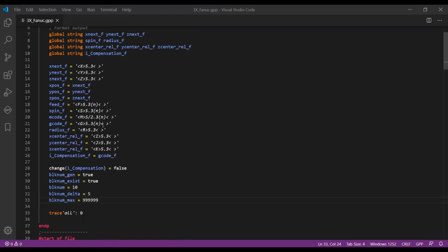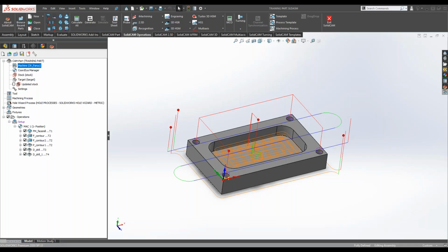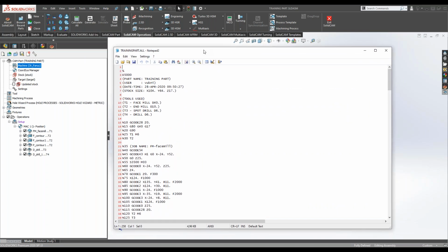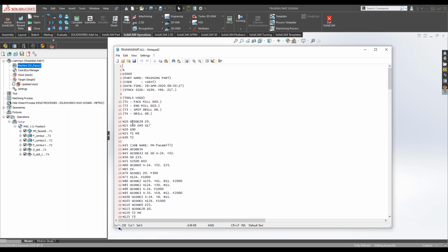We have our G-code format, and here is the prefix and postfix. Postfix is just an empty space, just to separate each coordinate. And if we say here just Gcode and save it like this, let's generate the G-code. Let's close all of these previously generated. Let's generate. Okay, now you see that we have Gcode every time that G format is used.